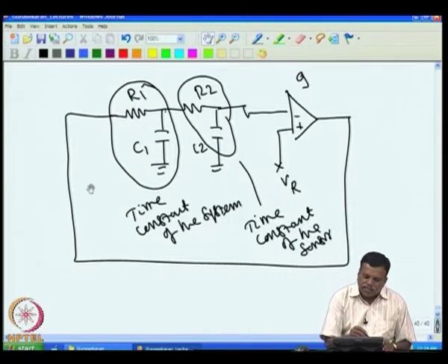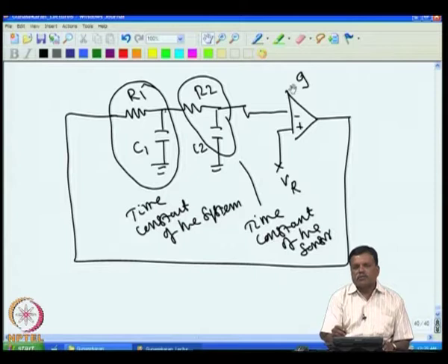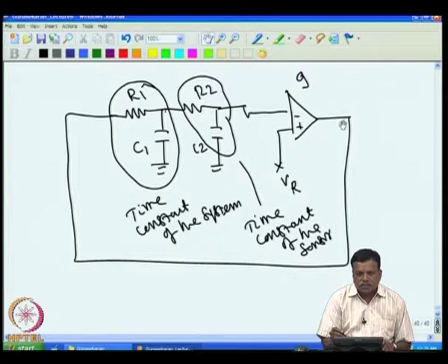Now, if I have a system like this, naturally it will oscillate, because if I increase this, the increase takes place with a time delay, and even the temperature in the oven is sensed only after again some time delay given by the sensor. Because of that, by the time it reaches the actual temperature, the voltage here has already gone much higher, and the net result is the system will keep oscillating many times. Now, if the gain is sufficiently large here, of course; if the gain is less, it will not oscillate.